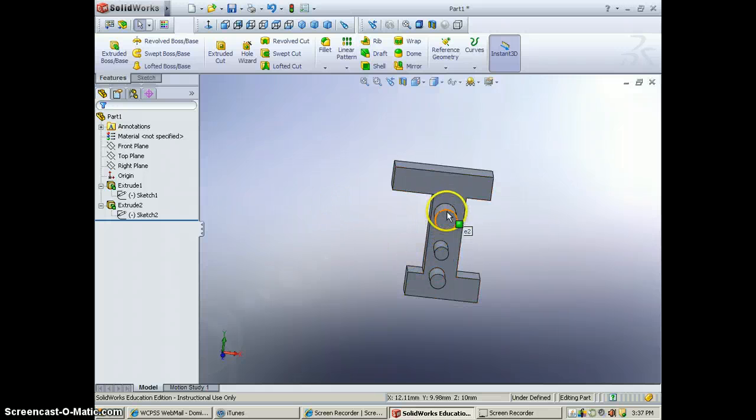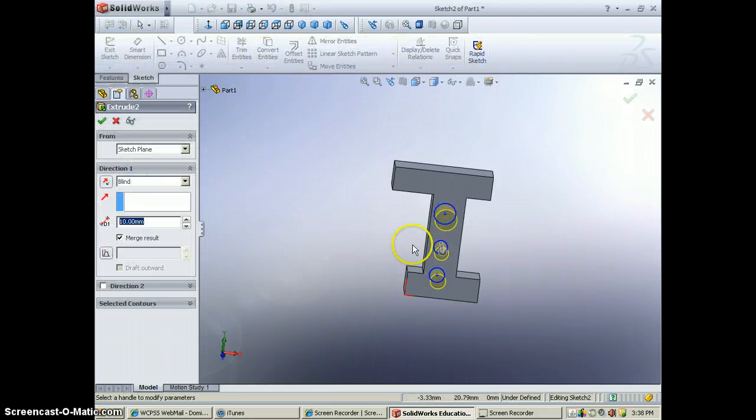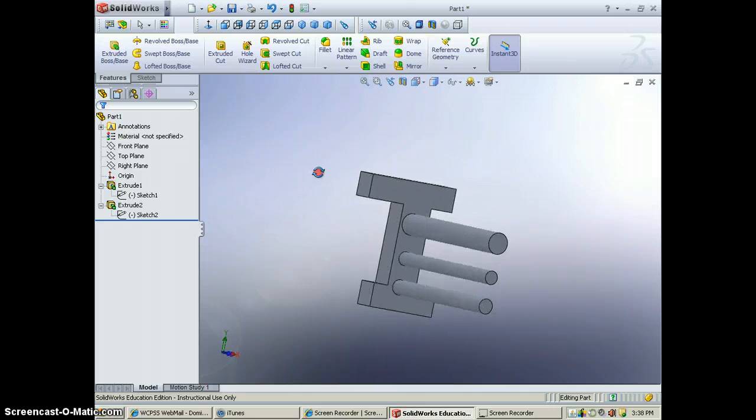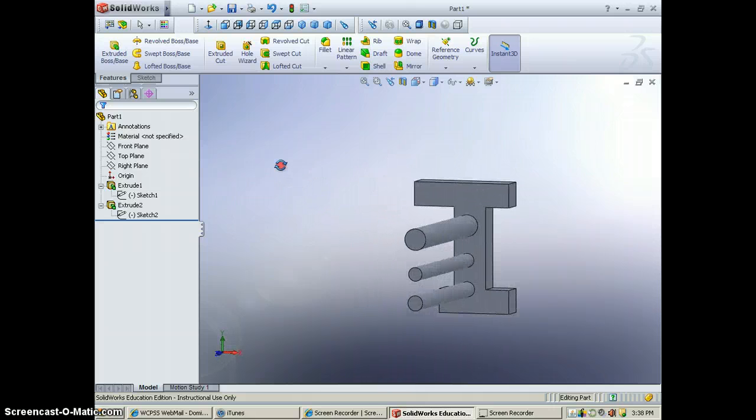If I want to change the length of these cylinders out, I'll have to go to the Extrude 2. So I click on Extrude 2, and instead of editing the sketch, I edit Feature. And I can change that here, or I can take the tip of the arrow and move it back and forth. I can check that out, and that one actually doesn't need rebuilding. It's done, but I can hit rebuild just to make sure, and there goes my object.